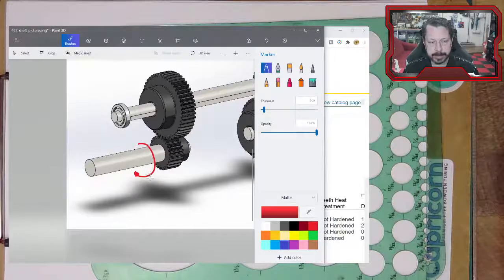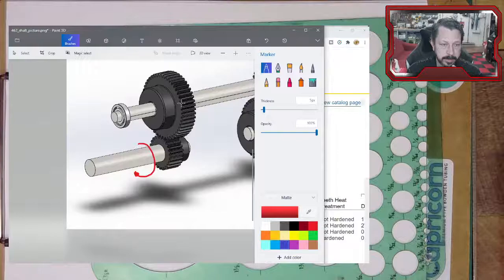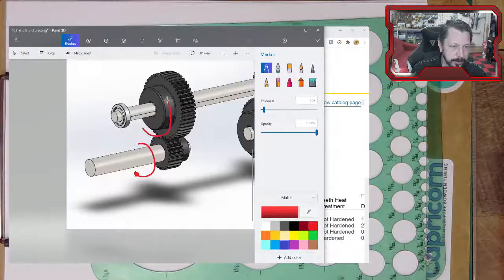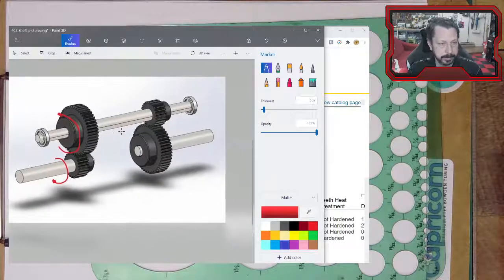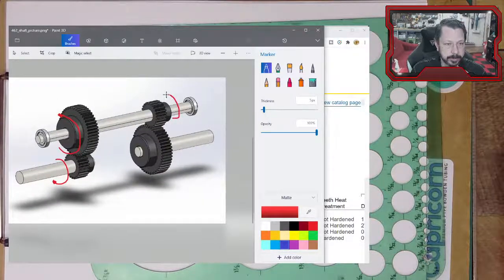So if I have 10 foot-pounds of torque here as an input torque, then I'll multiply that by 2-to-1 to get to the next shaft, because I'm reducing the speed and multiplying the torque. So this gear is going to be rotating. If this one is spinning, I've tried to draw that clockwise, I guess, so this one would go counterclockwise, and then see how there we go. That would mean this one's also going that same speed and torque and direction.